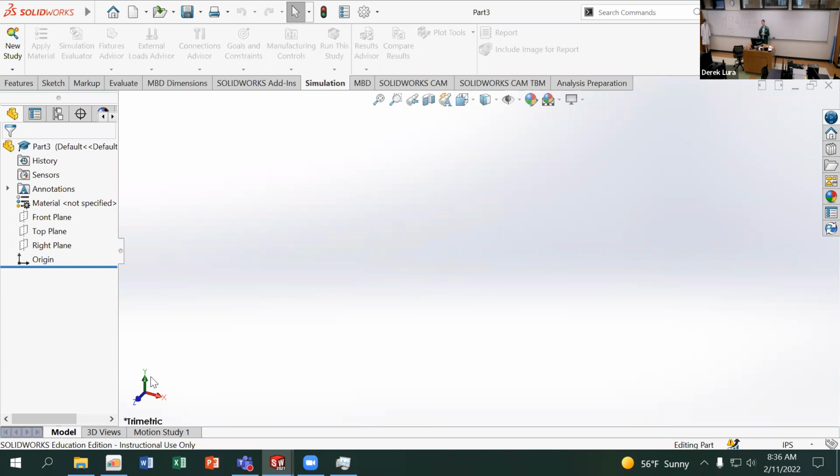So using a 0.2 millimeter layer height and all of the default movement speed. You can't go in and say, I'm just going to make it move twice as fast and make it super thick, so I have a really poor quality but a bunch of material, and that's how I'll win. The idea is that you're using an appropriate set of settings for the printer, but trying to minimize the mass and the geometry to make that good.